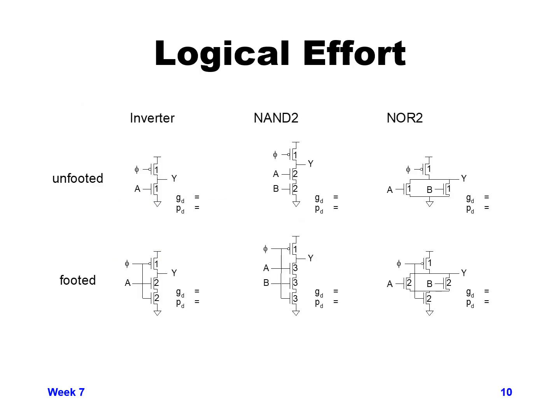So in this foil, we're going to go through the logical effort for domino stages, and I'll leave it up to you to compare that versus what the equivalent would be if you were using CMOS stages. If you want to pause here and figure out what the logical effort and the parasitic delay are for each of these stages, do it on your own first, and then we can go through the values.